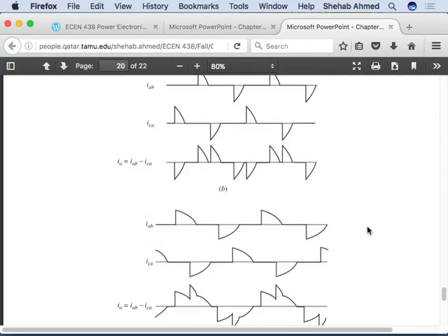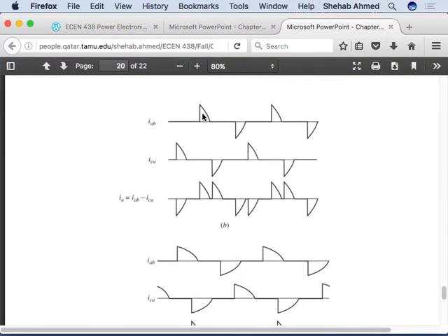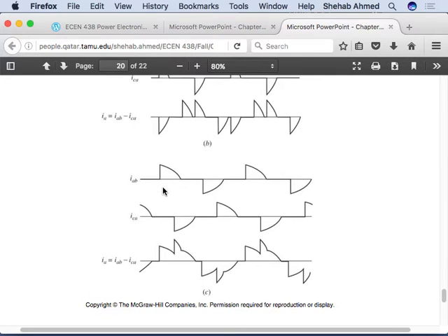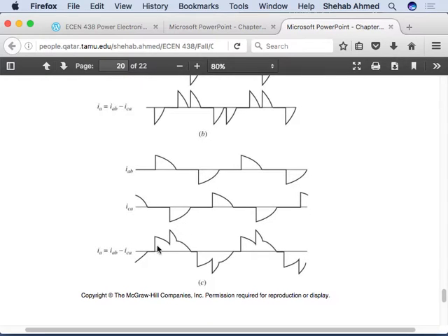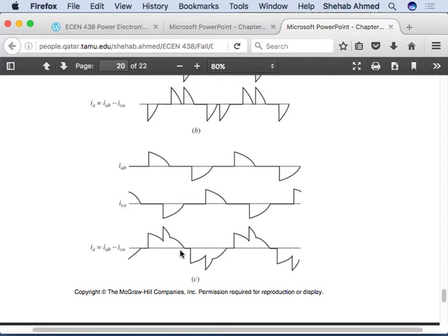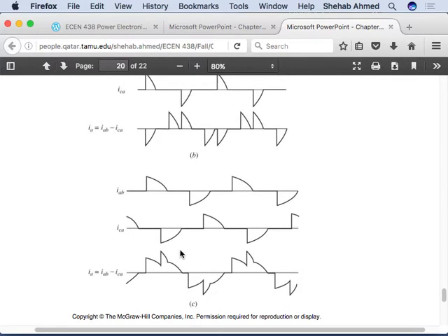So here, the case where the currents don't intersect, and we drew that. And then the case where you started the current, the alpha is smaller, so the current starts earlier for the IAB and ICA. There will be an intersection, so it will look more funky. I'm not sure if this will have more harmonics or less harmonics. You would have to do a Fourier series and analyze it. But it just looks different. Like, these are the two conditions.